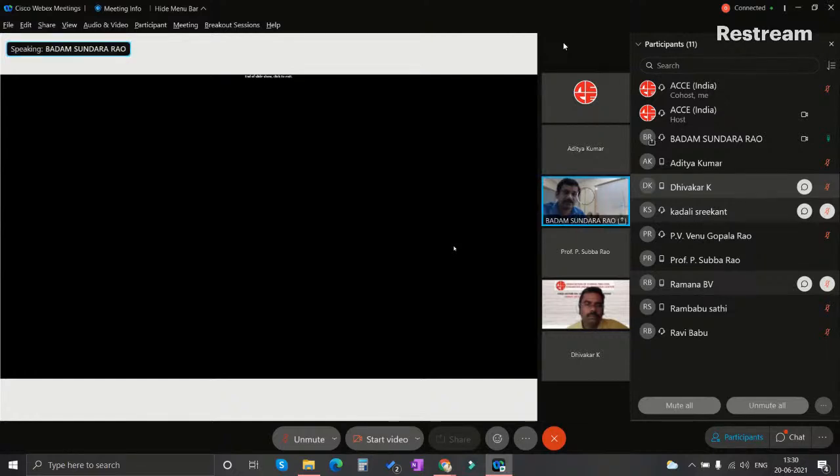Loose sands are highly sensitive, that's why I'm saying the site-specific criterion is always adopted. Generally, for the design spectrum also, while designing earthquake resistant designs for important structures like power plant structures, we go with the site-specific response spectrum. That gives a more elastic value and an in situ value that is more dependent upon the soil conditions and the actual conditions of the soil.